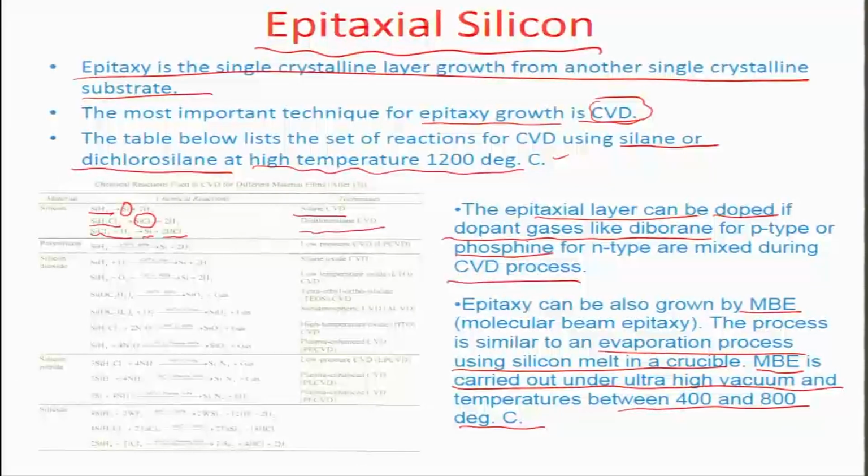So, there are many other chemistries also associated with CVD. For example, you could have silicon dioxide grown or nitride grown or silicide grown, based on what deposition chemistries you are using. So, this is also very well regarded as an additive manufacturing process, where we are talking about depositing layer by layer of material. Okay. So, this falls under the category of surface micro machining, as had been illustrated towards the beginning when we talked about such MEMS fabrication.